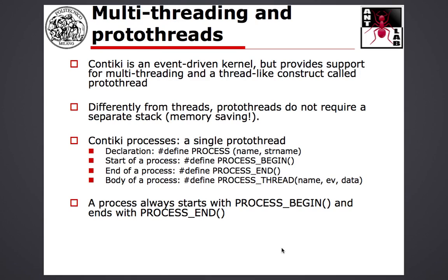And you don't have multi-threading. What you have is tasks, basically, in TinyOS. So you can reply to an event either by running some code or by posting a task into a task queue. Instead, in Contiki, there's always this sort of event-driven workflow, but you have also the support for multi-threading, okay? Meaning that you have actually different processes that you can write and you can run simultaneously. It's not like proper threads in a standard PC environment, but in Contiki you have this sort of protothreads.